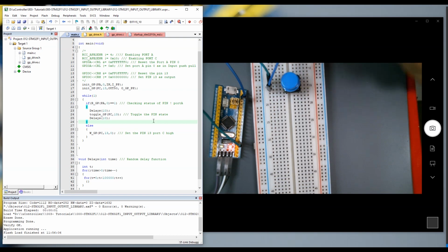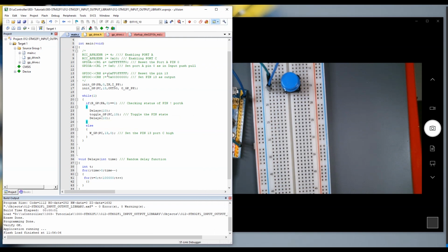Great. So we do have now a very compact code that will help us to quickly make our design from a GPIO perspective. And with this init function, we will also be easily setting up the alternative functions for the next modules, for example the UART or the SPI. So that's quite a great code to quickly and easily set up the next part.